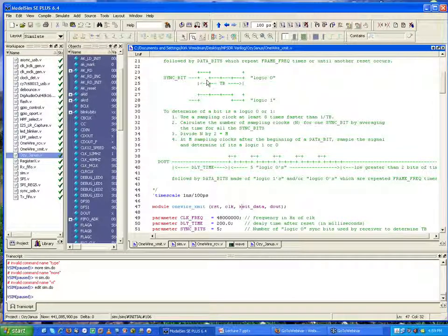Okay? And you can count, based upon your clock that you're using, how many clocks it takes between rising edges. So I could set a counter starting to count on this positive edge, and I'll show you how to do that. Anyway, you can start counting on this positive edge, you count until you get to this edge, and you record that value. Okay, it's so many clocks.